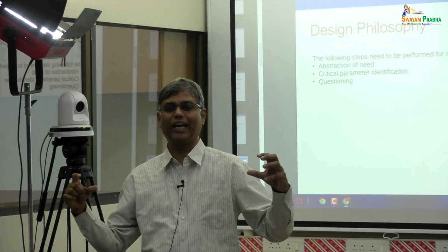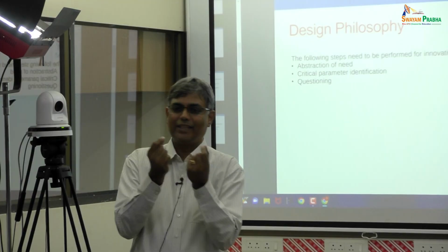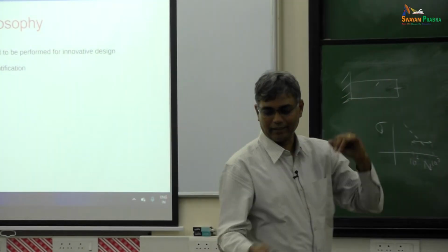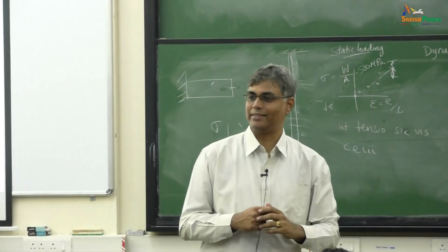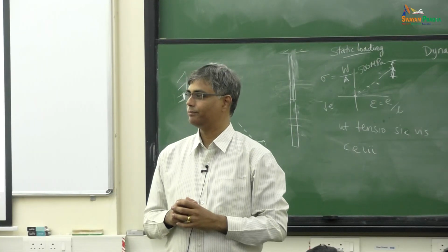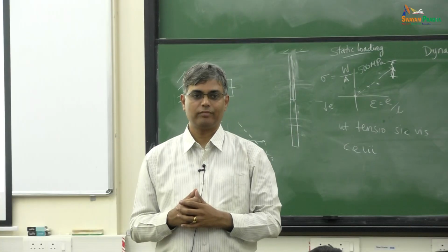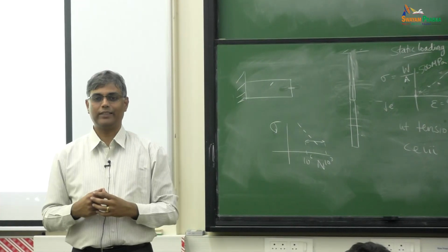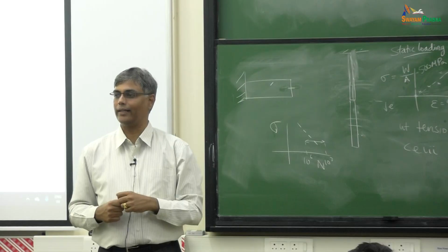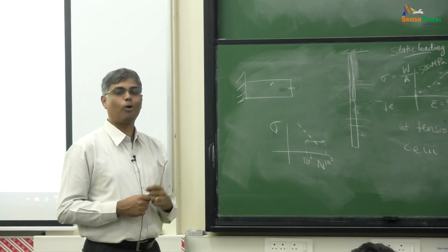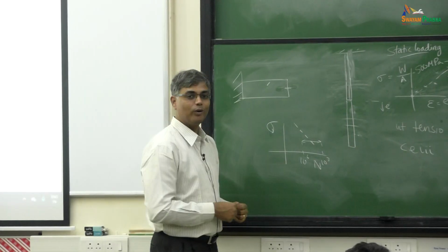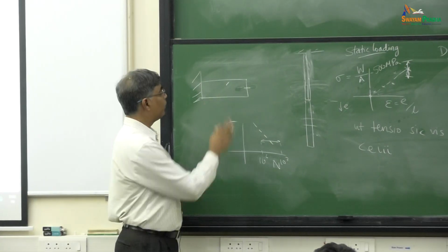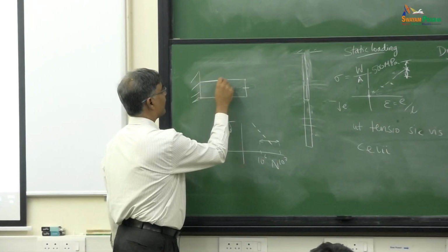You produce your material as carefully as you want. It will have some small void, some air bubble, something called a dislocation will be there, some particles will come and sit there. There will be some defects. That's a fact of life. And right now, the current sophisticated modeling approaches do not consider that. So why do we not do a simpler model? I want all of you to help me out with this calculation. It's very simple. I'm going to model this bar as a bunch of parallel springs.